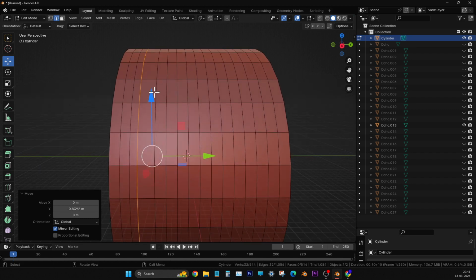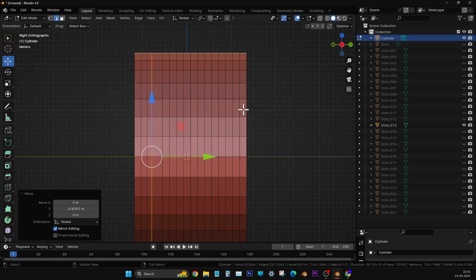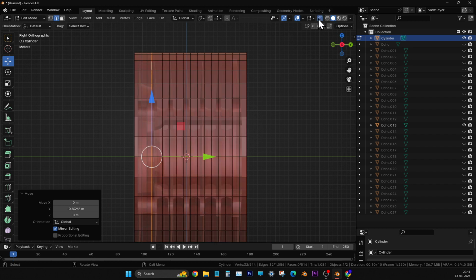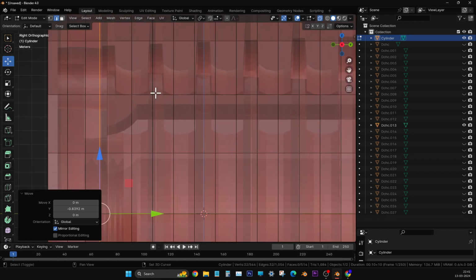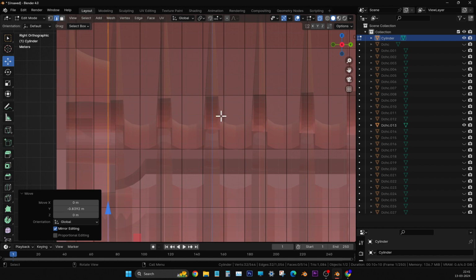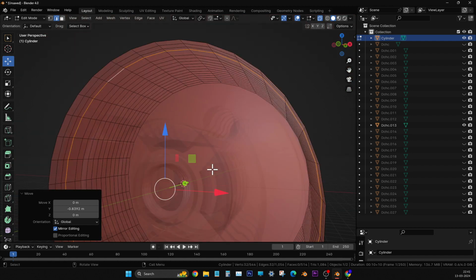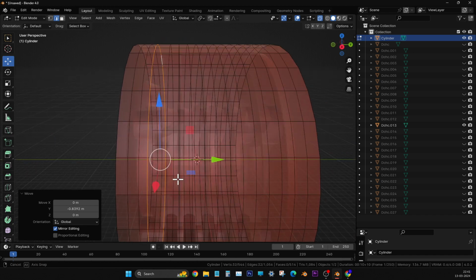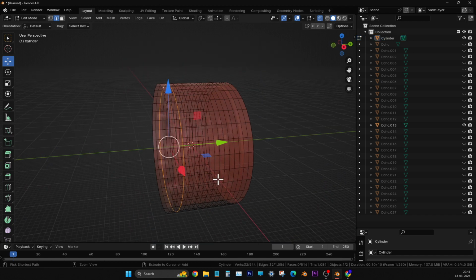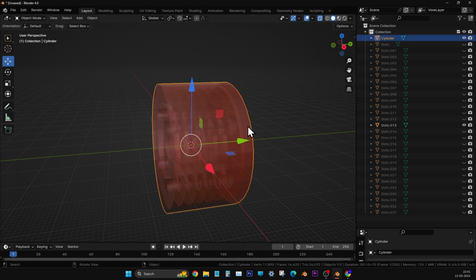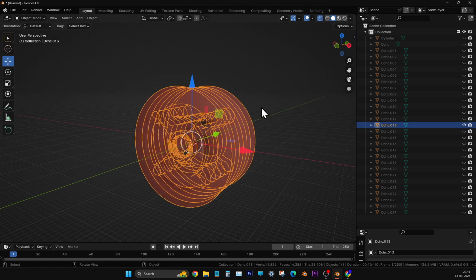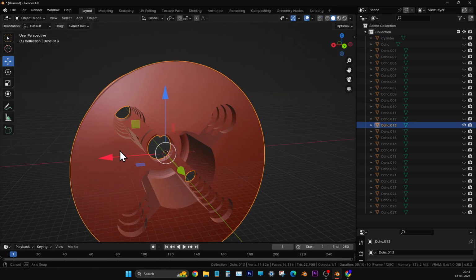I can only scale it, and wherever it is tapering, going inside, there I can add edge loops and scale it inside and keep it like this. But this inside hole won't happen. So how to do that? There is a workflow for it. Workflow means after what we should do what. So I'll just hide the cylinder and first extract some curves from here.